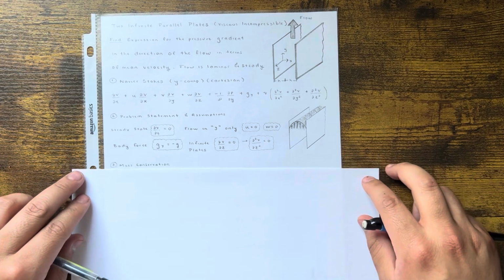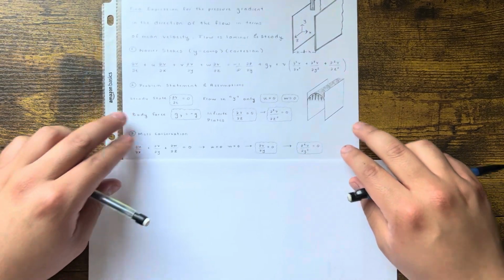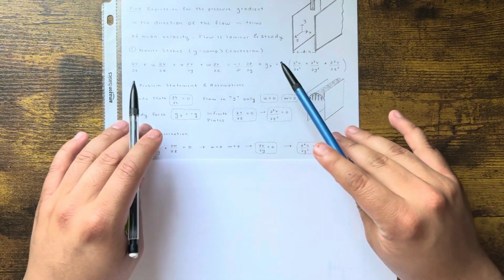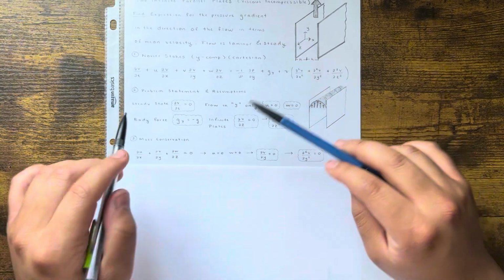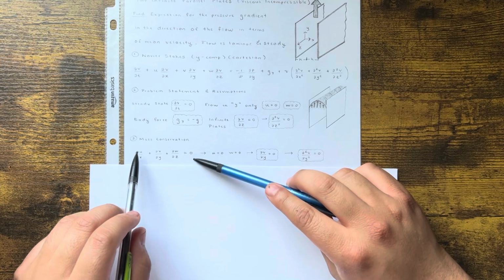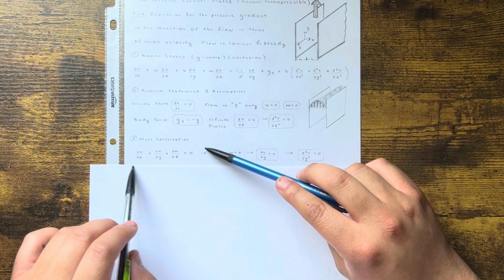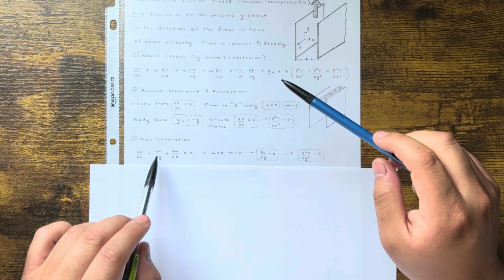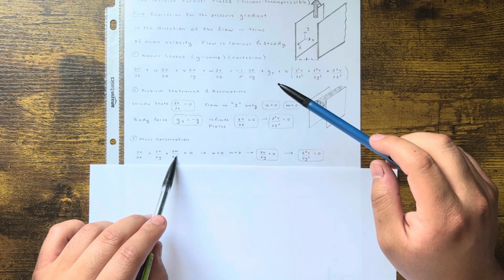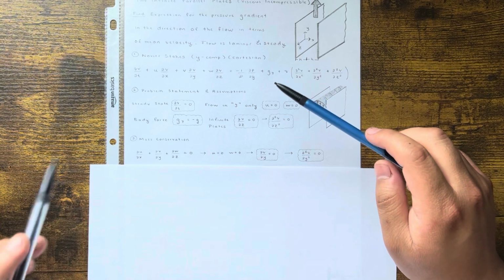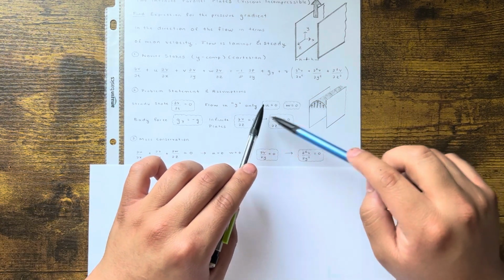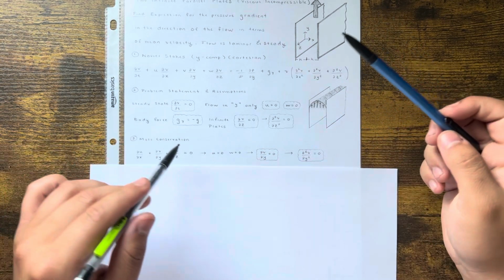So now we go to the conservation of mass, to eliminate even more terms. We know mass is conserved in the system. So when you start applying it for Cartesian coordinates, this is the mass conservation equation: the change in u with respect to x plus v with respect to y plus w with respect to z, all that's equal to 0. But we know that u and w are 0. So anything in the x and z, there is no velocity profile.